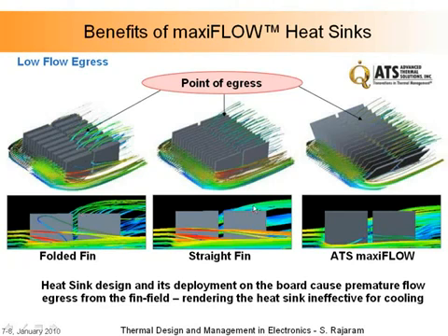In this one, it is also separated, whereas in this particular design, you notice that all the flow shown by these colored flow vectors is inside the fin. So this is the design you want to choose, because now when the air goes in the fin, it's going to cool the fin. And when the fins get cooled, it's going to cool the device.